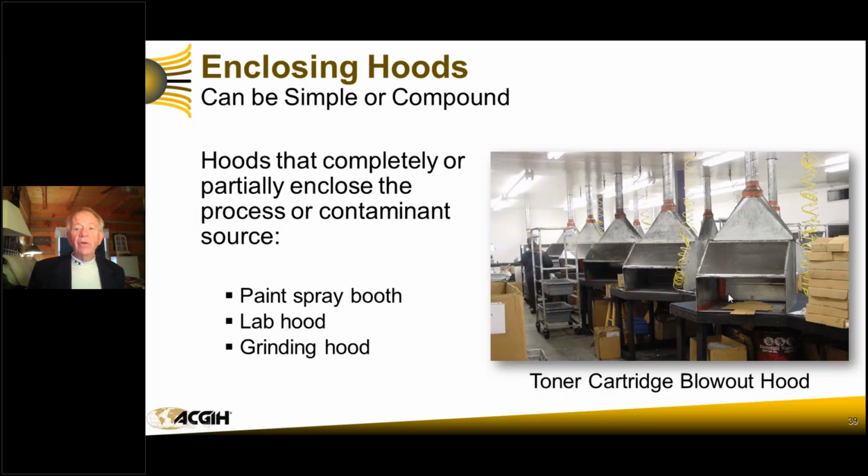And what we know is that this is a hood that completely or partially encloses the process or contaminant source. These are always the best sources, best control devices in the control hood designs. They are so good that the most successful hood of all times is designed this way, and that would be a paint spray booth. There are millions of them probably around the world.